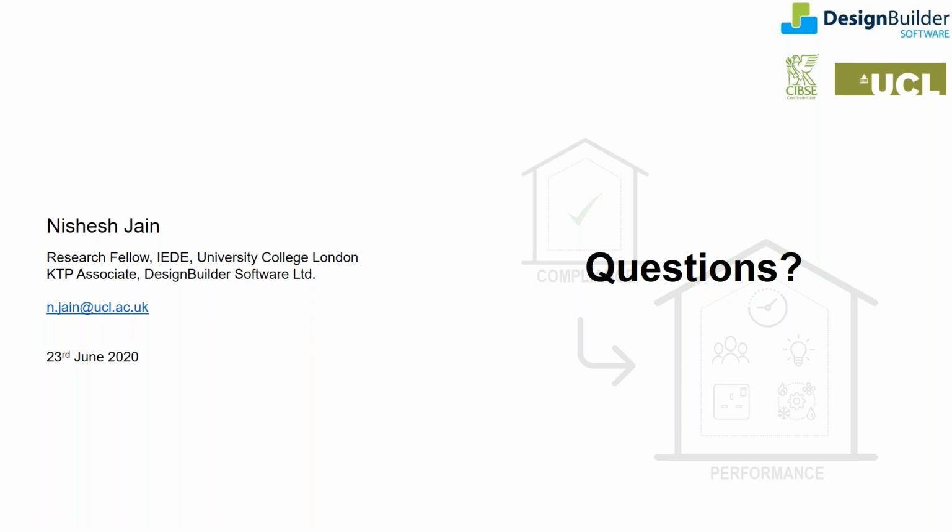The default which NCM gives for domestic hot water in NCM calculations is a lot, and that is something which you can modify in terms of the storage capacity and the type of losses which would be there for hot water. For those, obviously NCM values were used, but when you're doing TM54 analysis, it is up to you to get an actual understanding of how much would be used and then modify it.